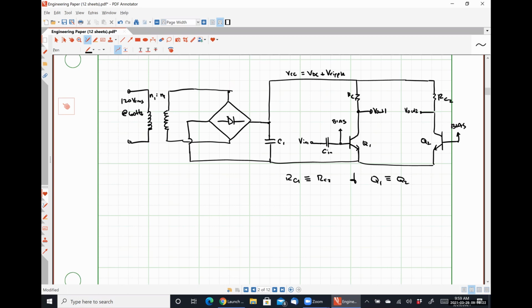For this particular system, as our input signal gets larger, our collector current should also get larger, right? For small signals, if this gets larger, then VBE is getting slightly larger due to our small signal input, which is causing more current to flow here, but the amount of current flowing here is fixed.